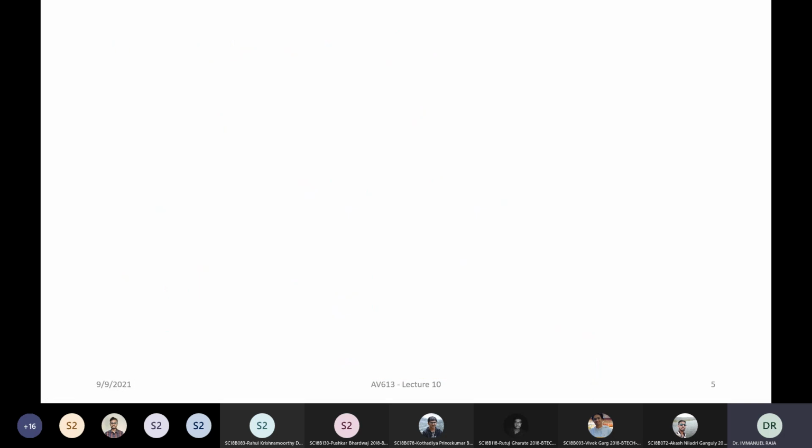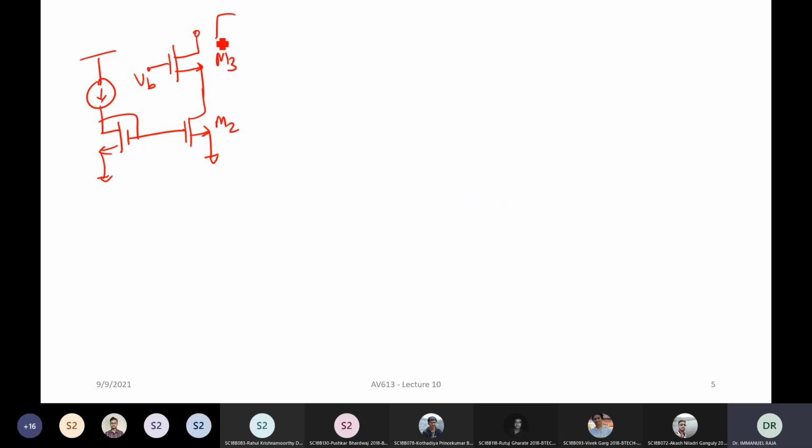Okay. In other words, an easy way to remember. So let us analyze this expression. So basically, what did you have? You had this circuit. All you did was you added this M3 transistor on top of it. And now suddenly your R out here, an easy way to remember this expression is like this: R02, the bottom one, plus R03, the top transistor, plus GM, the top transistor GM, multiplied by R03 multiplied by R02. Okay. Now, look at this expression.